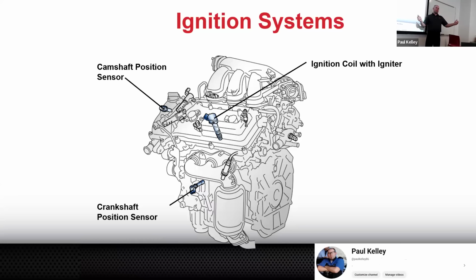Well, first off, remember I said, if you're stuck on getting the spark plug out because your ratchet's not long enough, you really have no business trying to pursue the diagnosis. Diagnosis takes a lot more understanding than getting a spark plug out. So pause right there. Let's readdress. When I knew it had a primary ignition voltage code, the primary issue, that's all on the small 12-volt little wires, right? So I said, forget the spark plug. The spark plug could cause a misfire, yes, but the spark plug will never cause a primary ignition voltage code. So just leave the spark plug alone, stop wasting time, get a longer ratchet and just be done with that.